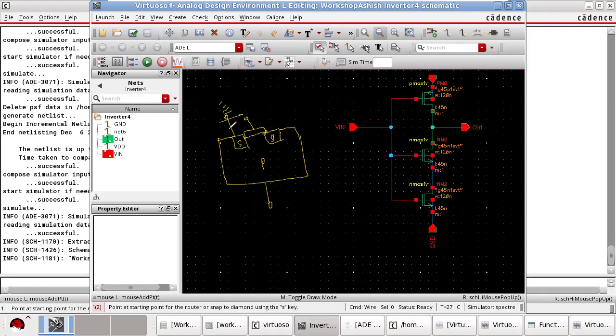When the source is on the ground and the body has some other voltage, then this is N, this is P, this will either become a forward bias diode or a reverse bias diode. To make it neither of them, we actually connect these two so that we can avoid becoming a diode. So either we give it a 0 manually or we connect both of them. This will actually almost behave the same way. So I have connected the source with the body. Okay, sir. Right?